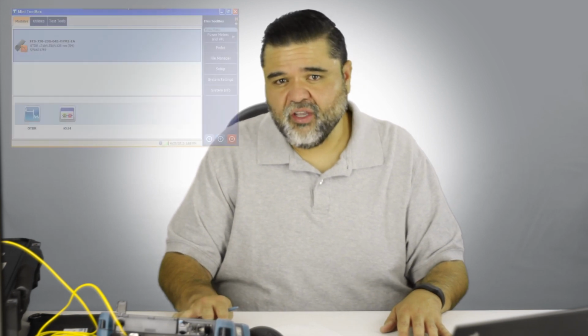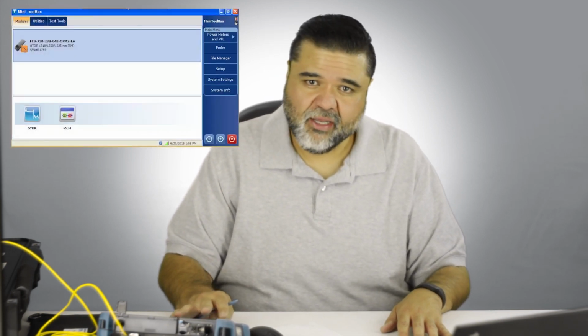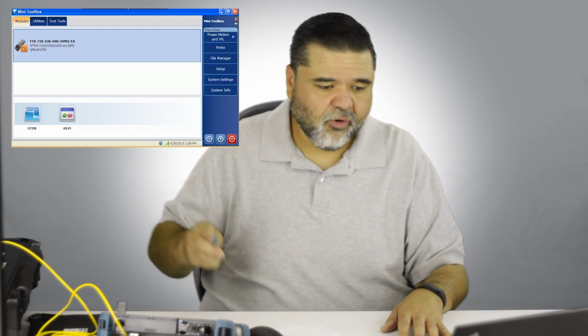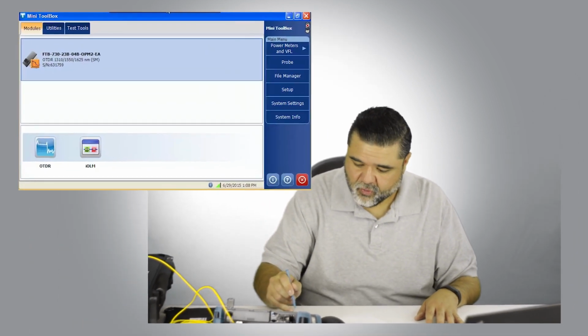I did a different 15-minute or less training video talking about fiber cleaning, so we're not going to get into that, but it is critically important to understand that fiber cleanliness is really paramount when you're testing fiber optics with iOLM or an OTDR. So I'm going to go ahead and launch the application here. I'll click iOLM.